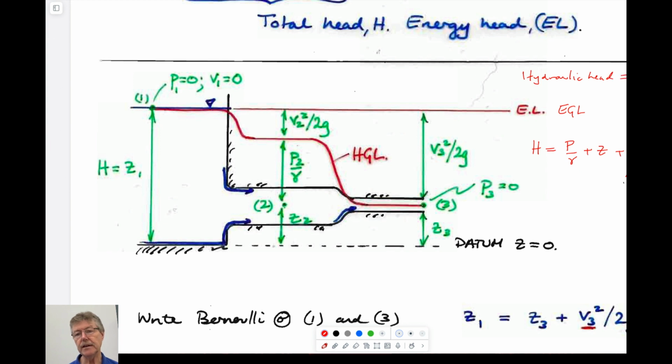And we call that uppercase H, which is given by the hydraulic grade line in this particular case. And so if you look at it upstream, there's 0 velocity, then v squared over 2g is equal to 0. If you're at the surface here, the pressure is equal to 0, and therefore the elevation of this point, h, is equal to z1.